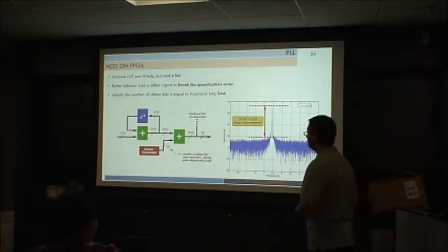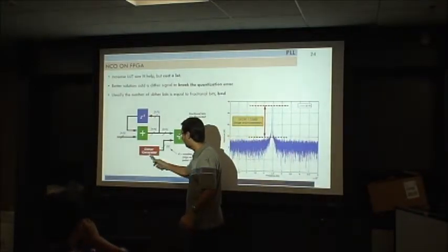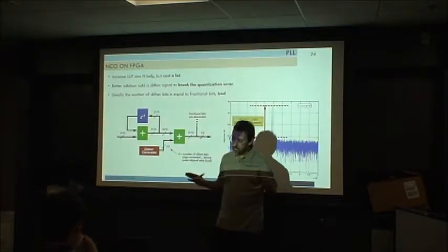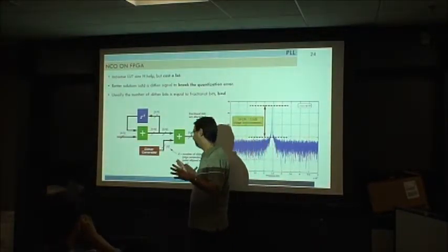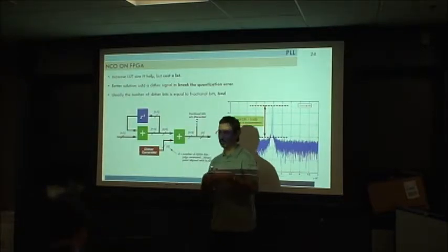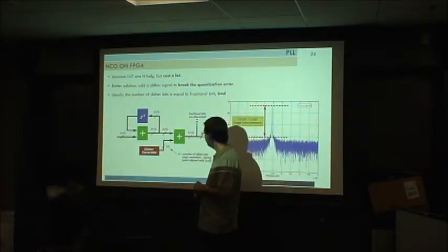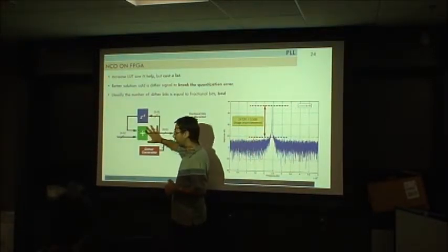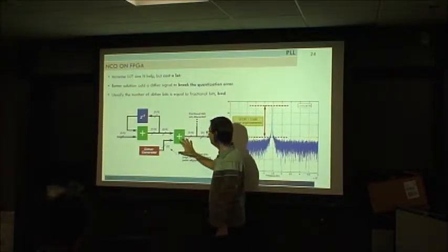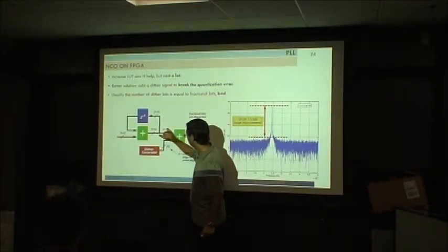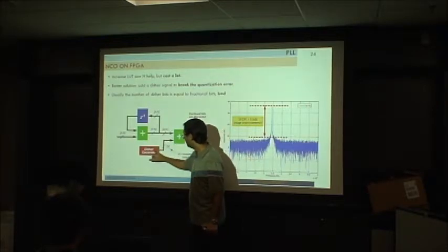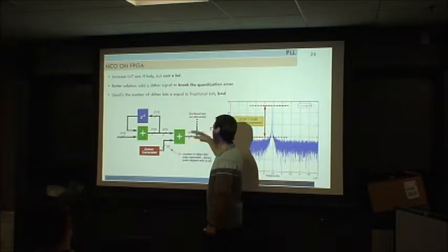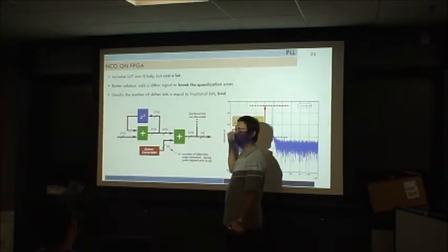So basically the theory calls it a jitter generator. This is basically a random generator that could be a PN sequence or some other kind of random noise generator. If you see, this is exactly the same as we had before, but we are adding a little more complexity: to the fractional part, we are adding some noise with this kind of jittering bit. So at the end, this is the number that is going to the memory.